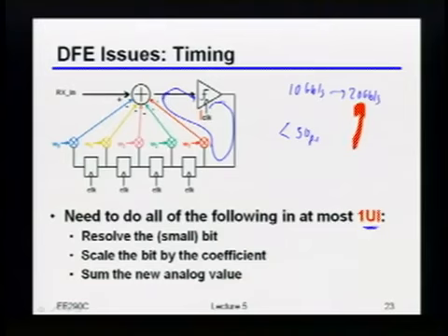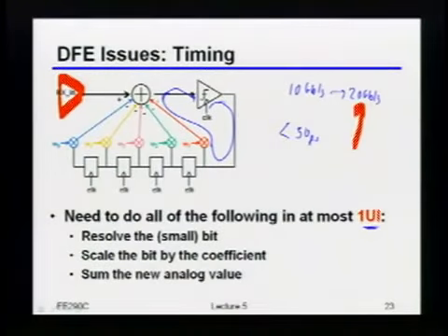Well, no. So, as I said, and I am guilty of this, for this lecture I'm mostly focusing on the communication side of it. You're absolutely right that from the standpoint of how you build the circuits, it's not immediately obvious that the noise you've added from this transistor is all that much better than the noise that would have come from something else at the very front end. So again, this has a lot to do with looking carefully at where the noise in your system is really coming from. But you can imagine that if I have some linear equalizer or something with gain in front of you, then if you've done a good job with the chain, usually your noise will be dominated by the front end stages and not by this later stage here. It's not universally true, but generally speaking, that's the case.